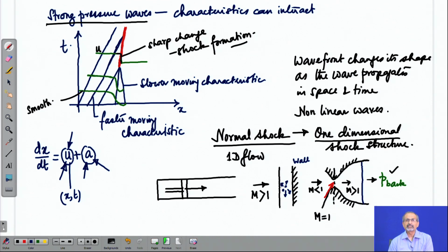This is happening because increasing number of molecules are impacting with the wall, colliding with the wall, and thereby feeling the presence of the wall, they collide back with their neighbors, trying to propagate this information upstream that there is an obstruction. At what speed does that information propagate upstream?